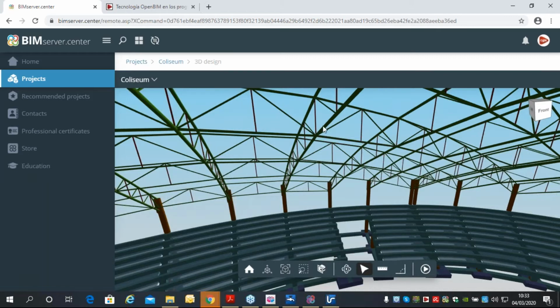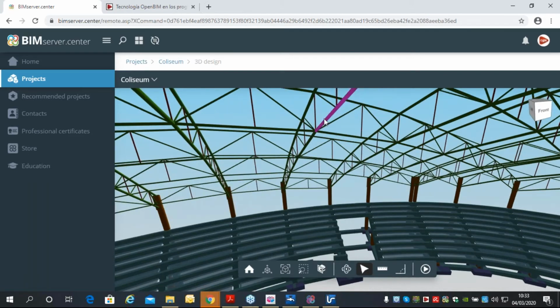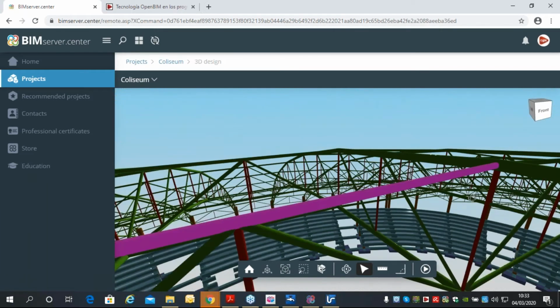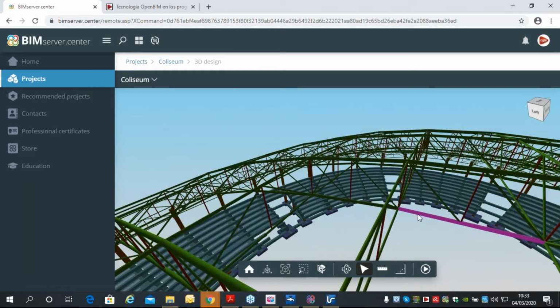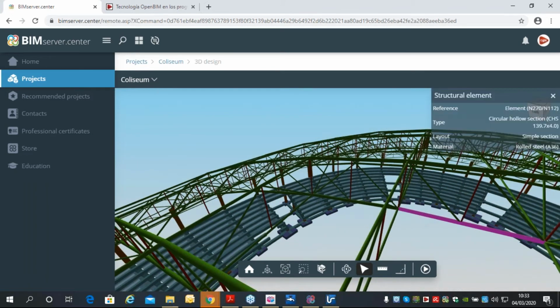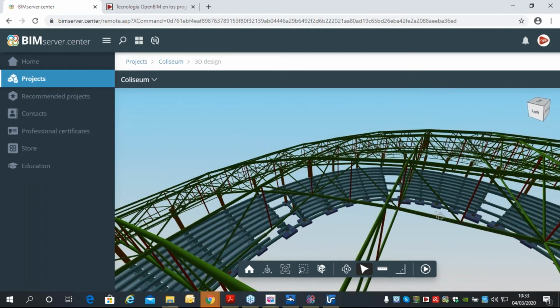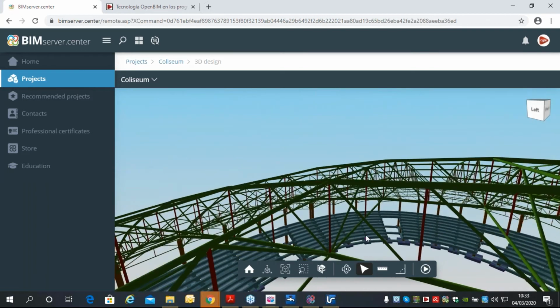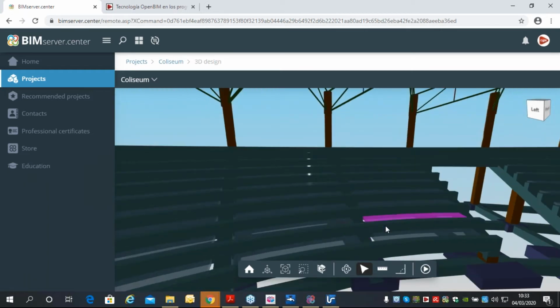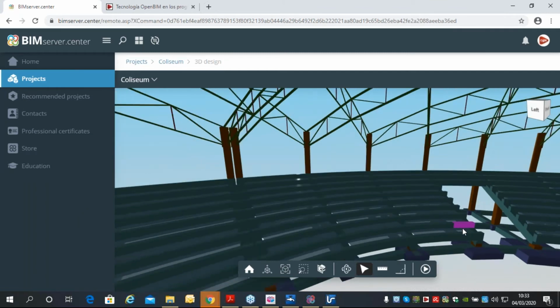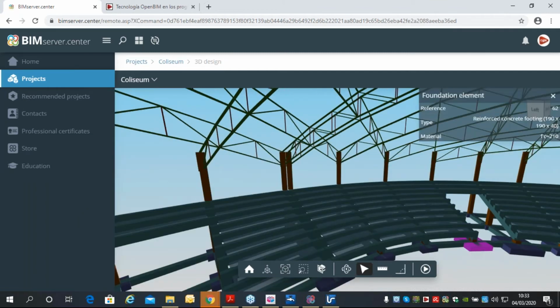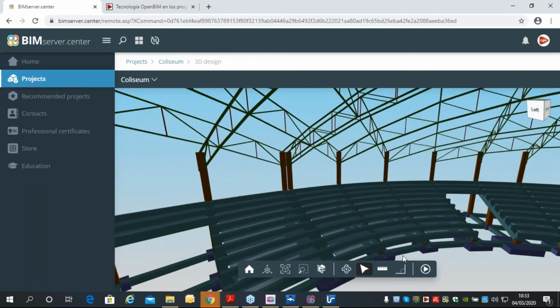Also, we have used IFC Builder in order to generate the BIM model, but you could use any other, ArchiCAD, Revit, or Allplan models, in order to communicate with our design tools. And also, you have site plumbing solar systems if you want to design solar thermal installations for domestic hot water support or heating support. Or finally, you also have the site plumbing schematic diagrams in order to design, starting from the water supply design, your schematic diagram of your water supply site.